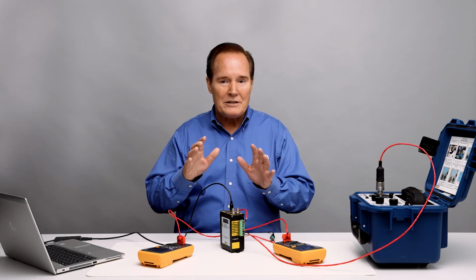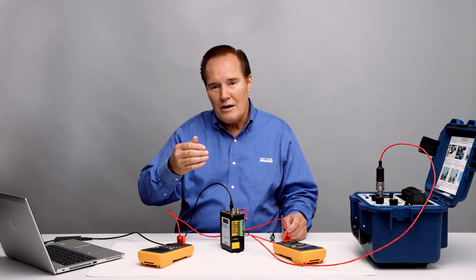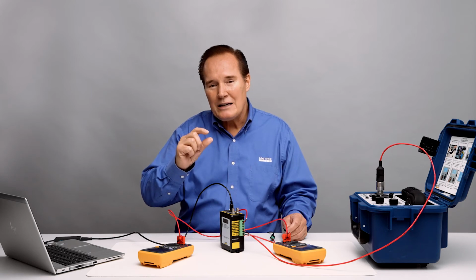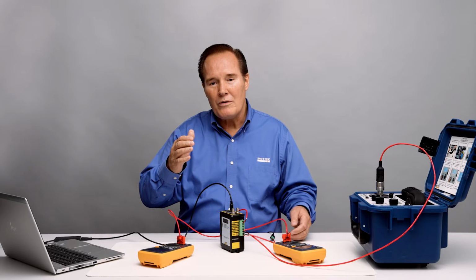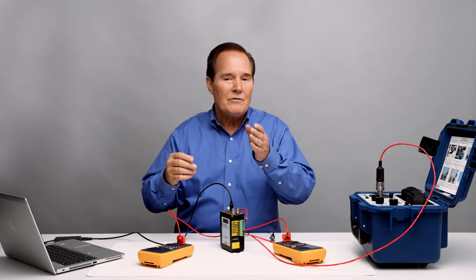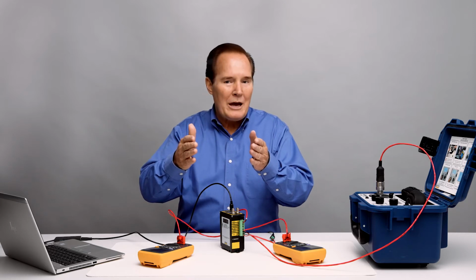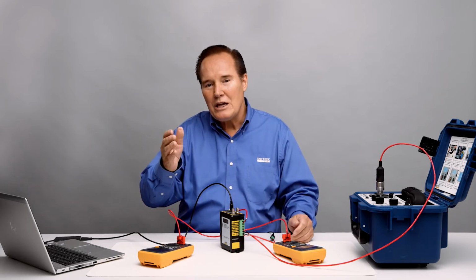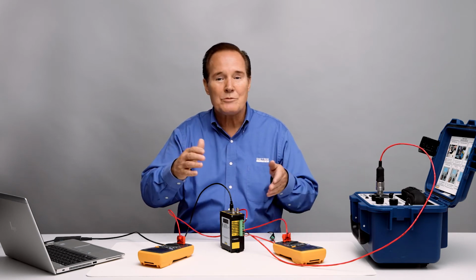Now you have to remember how an impact system works. What we do is we time for 16 movements of the compressor, 16 cycles, or 16 compression events. When you measure those 16 throws of the compressor, if there's an impact, each impact will equal 1 milliamp. So on a scale from 4 to 20 milliamps, 4 milliamps are no impacts, 12 milliamps would be 8 impacts, and 20 milliamps would be 16 impacts. That's the most you can have. Usually if you have 6 to 8 impacts, you should start looking. More than 8, you should start thinking I should shut down that machine because I have a real problem. Above 12, certainly shut down the machine. But that's how you set it up.